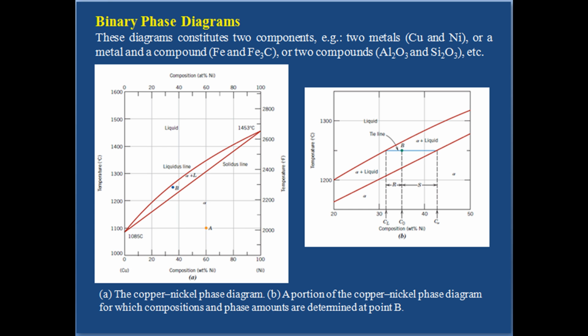A solid solution based on a pure component and extending to certain finite compositions into a binary phase diagram is called a terminal solid solution, and the line representing the solubility limit of the terminal solid solution with respect to the two-phase solid region is called the solvus line.